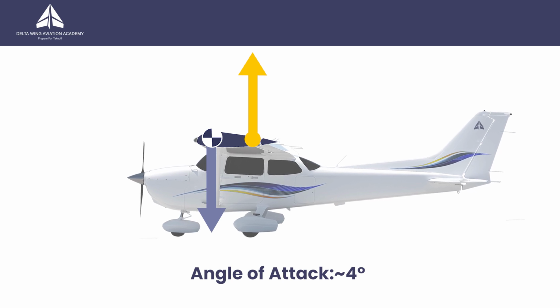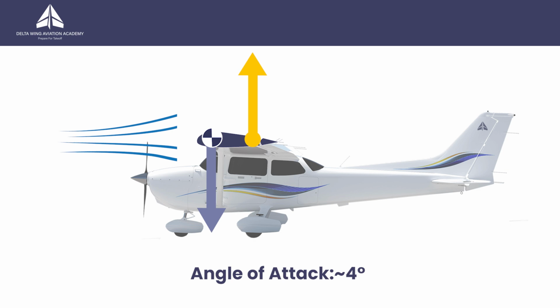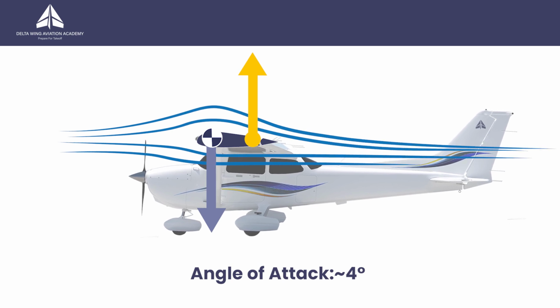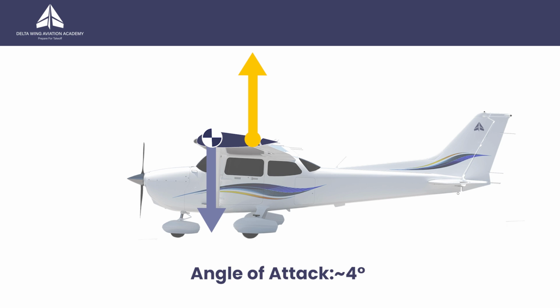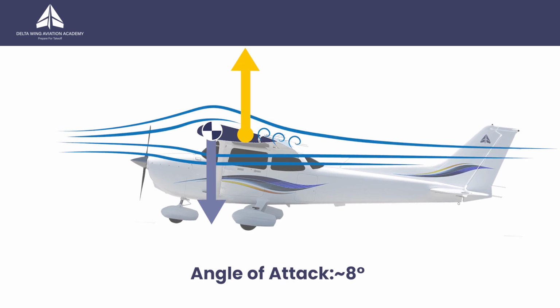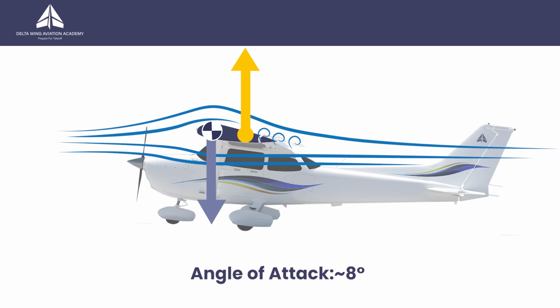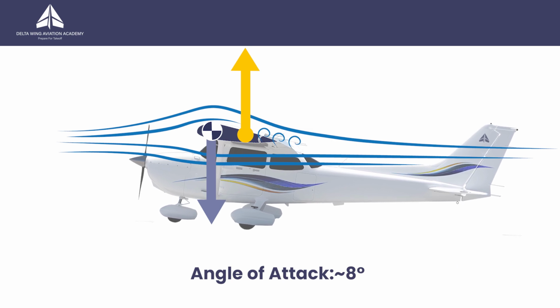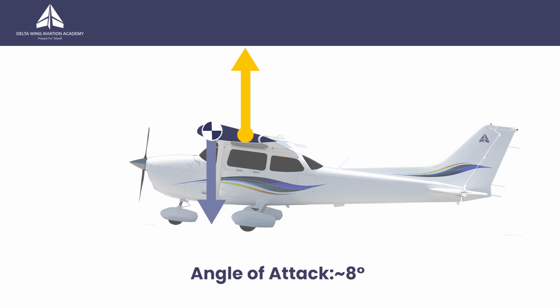In straight and level flight, lift equals weight, and the airflow is smooth along the wings. As the angle of attack increases, the top airflow becomes turbulent and less effective at the trailing edge of the wings. Consequently, the lift vector moves forward where the stronger lifting air pressure system forms.